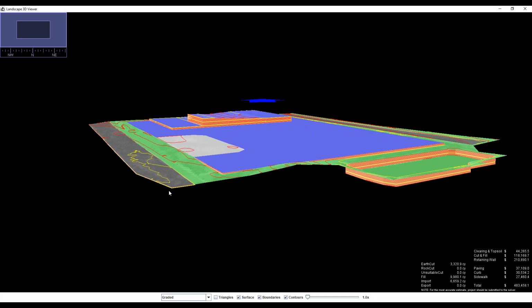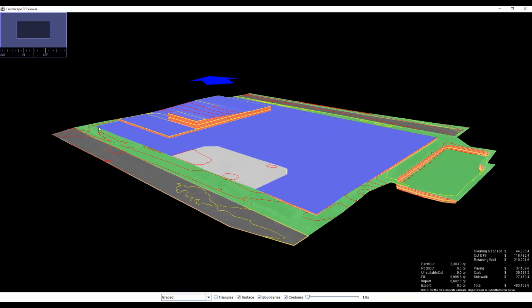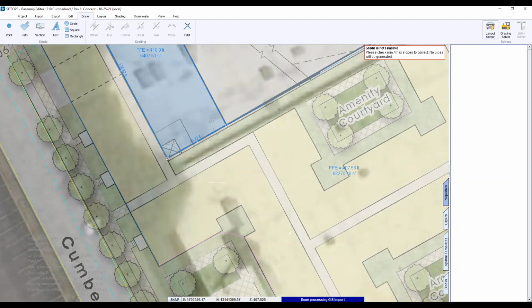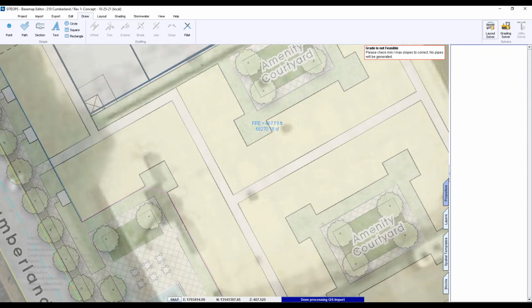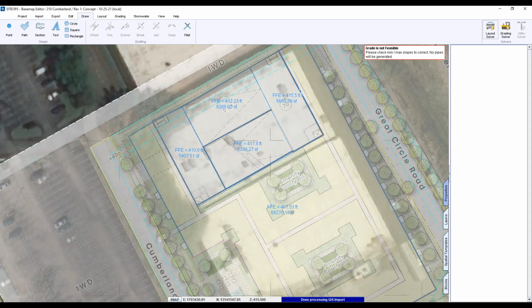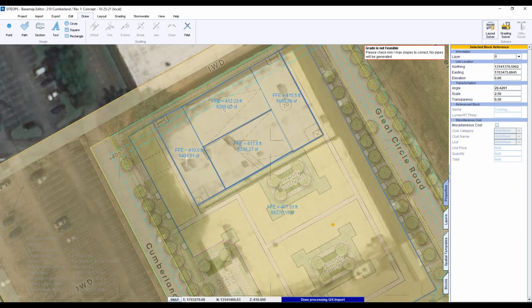So then you're like, okay, I saw that I had a slightly higher point over here. You guys don't really want to bury anything. They want to sit up above a little bit. So now we've set up a little bit, and it gave me 407.5 as your optimal finished floor elevation. Again, if I was really doing this, I'd go fix these 2 to link one here, and then this one would be 5.5. You could link this one here and have it be 5.5 over. So that would create your parking deck the way you want it to be.